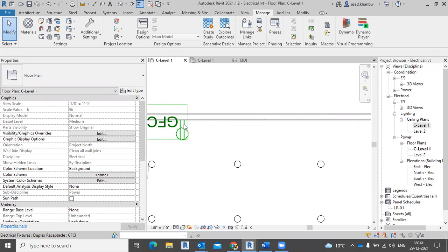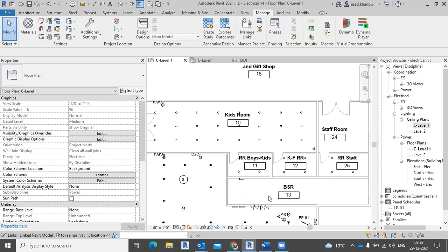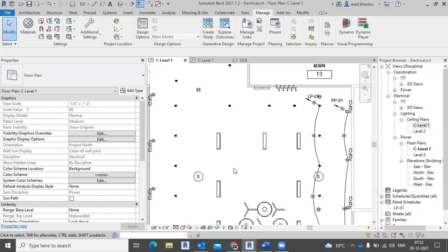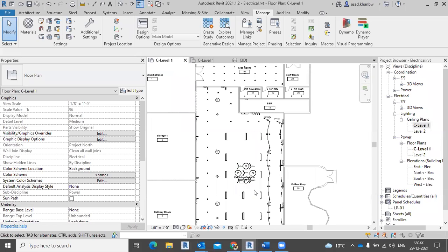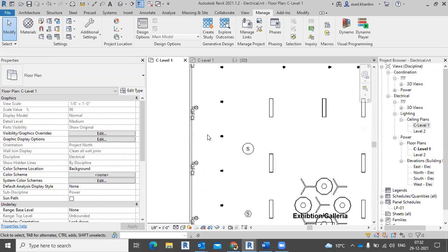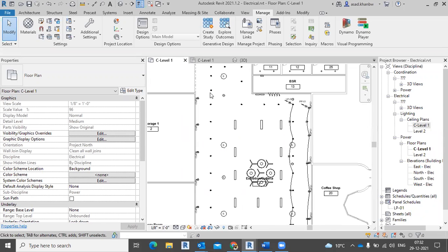Like I told you, if we use halogen, for example, at this place, it will generate a lot of heat, and that is not good if we have things using oil paint. If the things kept inside this space are sensitive, then it's the heat intensity, like 3000 Kelvin, 4000 Kelvin, that generates a lot of heat. So we need to keep in mind that it is not crossing the threshold value.